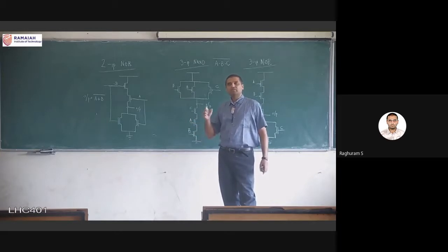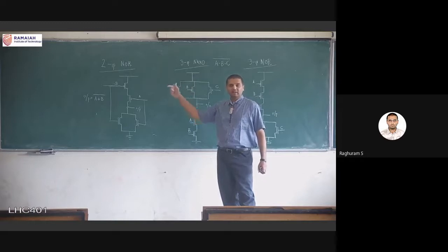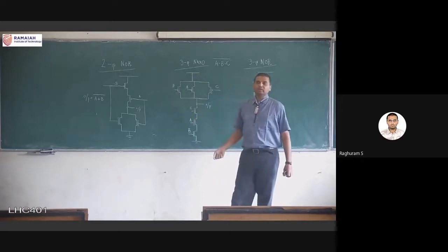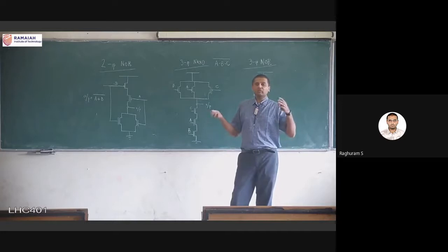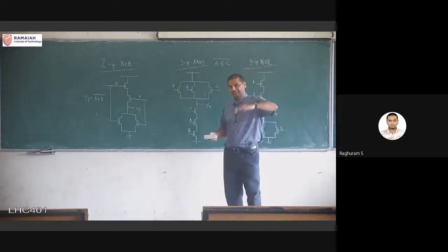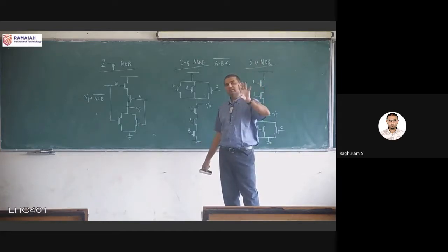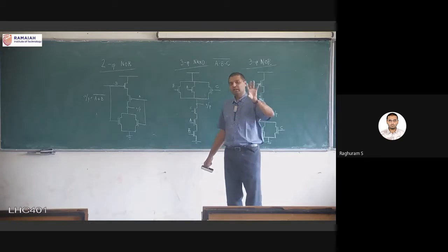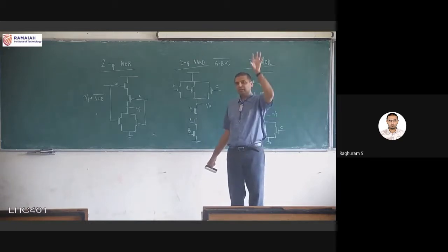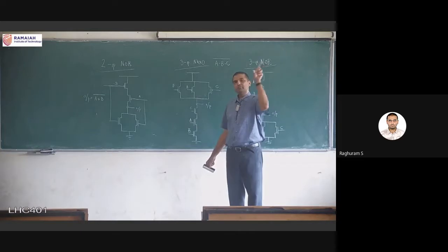But generally, when you have something like A and B and C and D and E and F and G, the way in which it will be converted into the netlist, if you remember the VLSI design flow, we have our RTL code, and the tool converts that into a logic level netlist. When it is doing that conversion, it will not convert it into one 6 input AND gate. It will convert it into a combination of a 4 input gate and a 2 input gate.